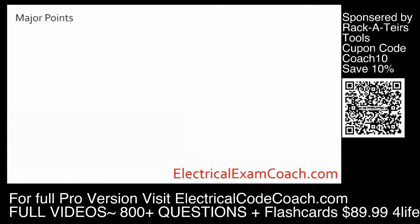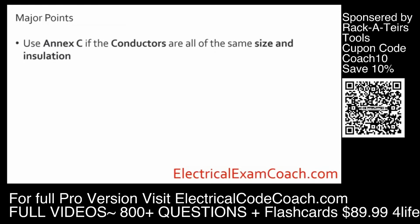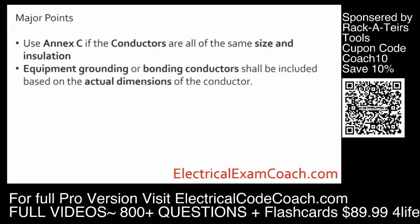Before we jump into the practice questions, let's go ahead and hit the major points. We're going to use Annex C when all of the conductors are of the same size and insulation. With dealing with equipment grounding and bonding conductors, they shall be included based off the actual dimensions of the conductor. It's not like we did in box fill. If there is a grounding conductor in that pipe, it counts 1 for 1, and all of them count. If you've got 10 of them, they all count.